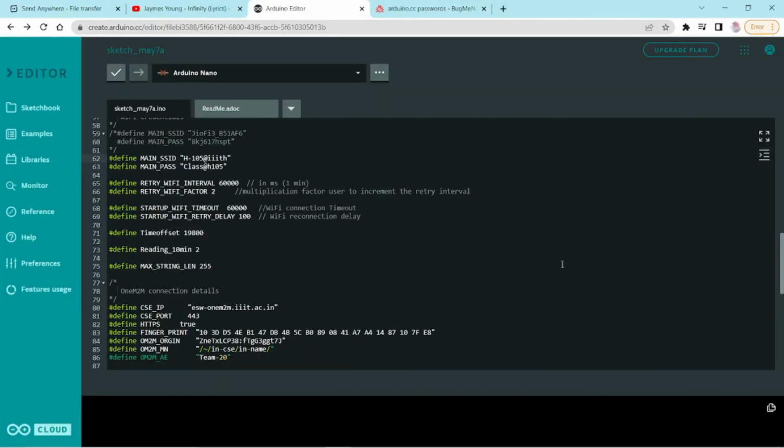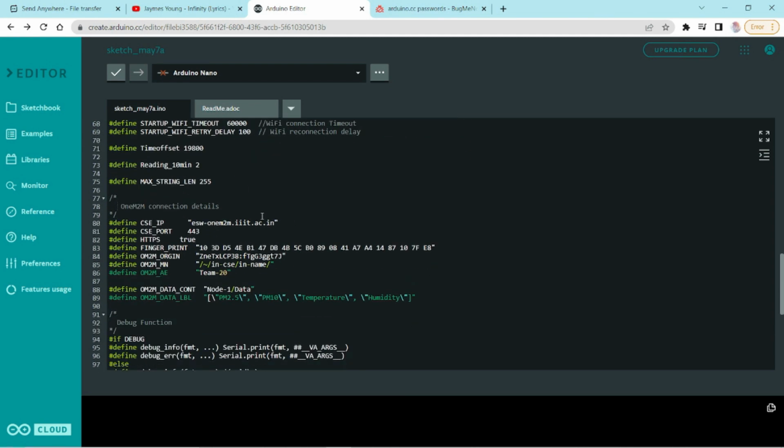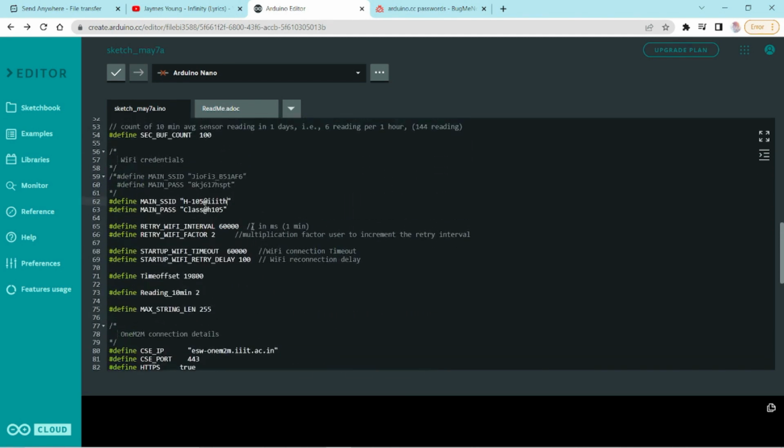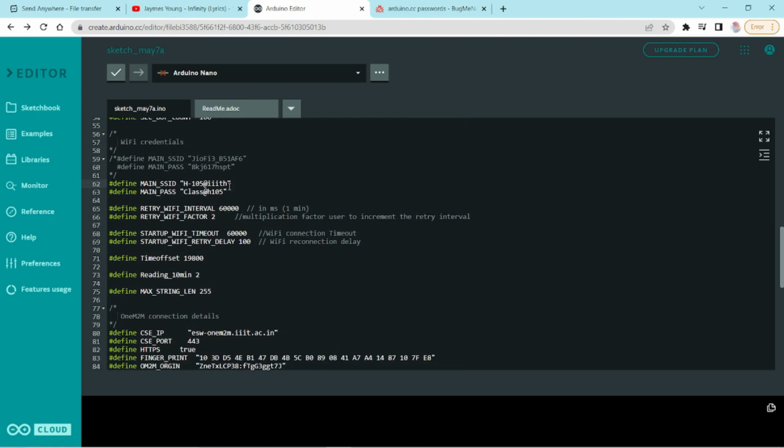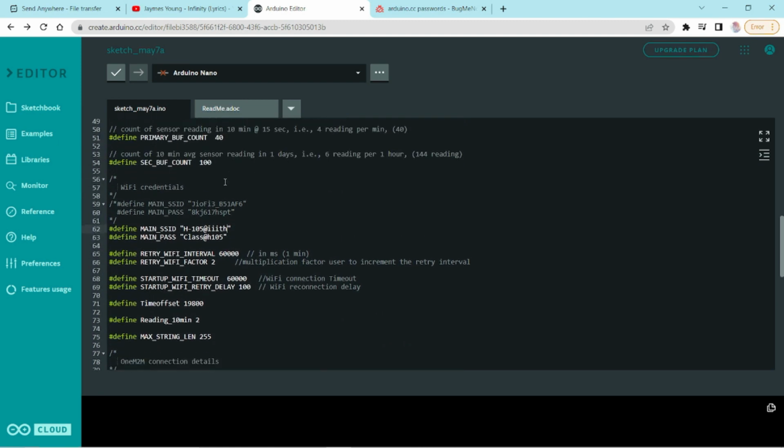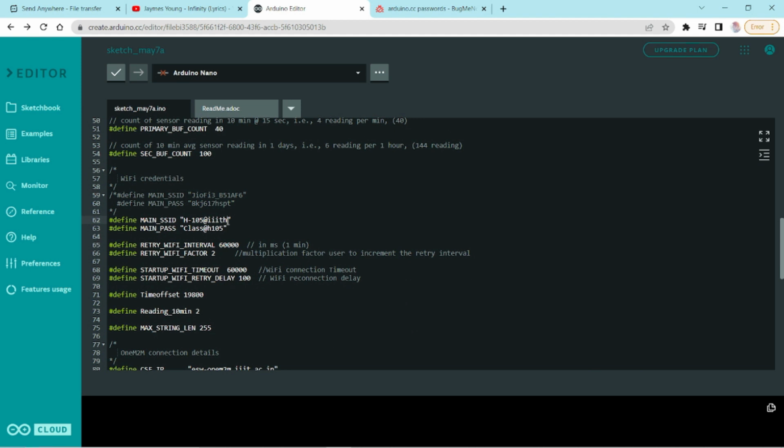Now that we saw the functioning of the hardware, let's see how the software looks. Once we install the node at the site location, all we need to do is change a few things in the firmware and update it. Just look for a Wi-Fi SSID and password nearest to the node installed, and change the SSID and password accordingly.